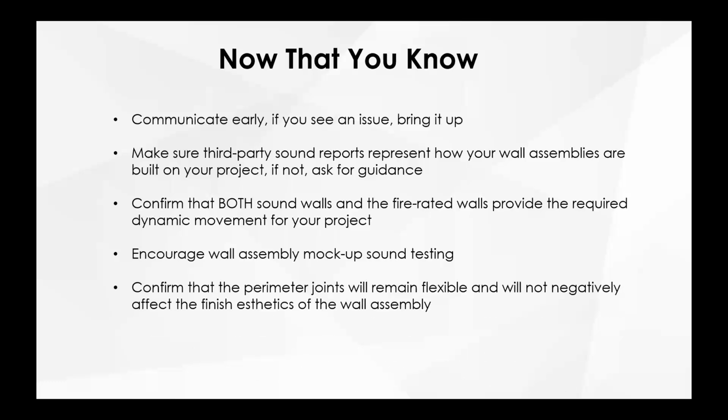Confirm that perimeter sealant joints will remain flexible and not negatively affect the finished aesthetics of the wall. So make sure that it's going to maintain flexibility. Typically, just so you know, if they were just testing acoustic sound on the perimeter, they test it the same day the sealant is installed. And if you've seen the way sealant, after it shrinks and cures, is a lot harder and it can split and crack. That will affect the STC ratings, but they never test it in that condition. They only test it when it's wet and freshly applied.